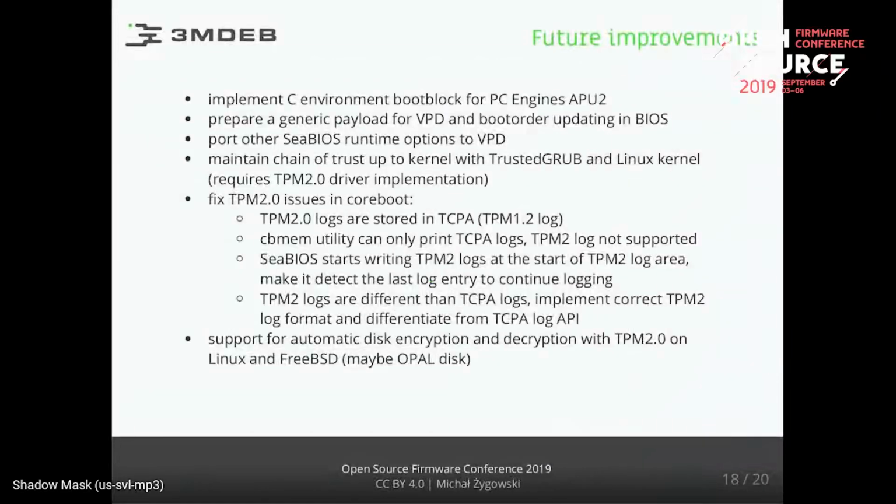The future improvements, sorry. So there are still some things to do, like implementing the C-environment bootblock for the AMD 16h family. I still need to prepare some generic payload to modify bootloader and VPD, like in the proprietary UEFI BIOSes, also for user convenience. Port all the coreboot runtime options to VPD.